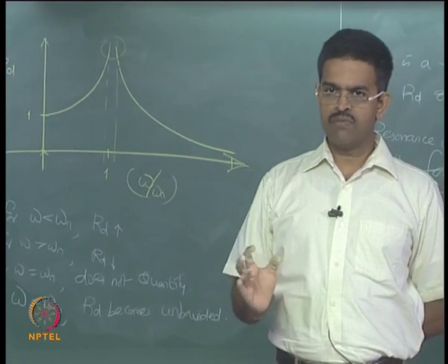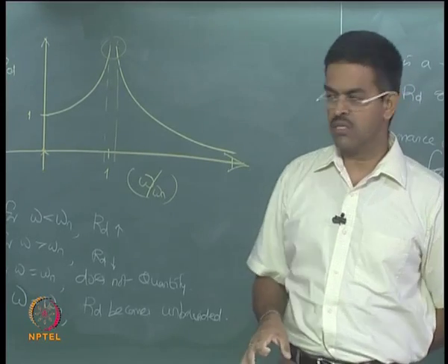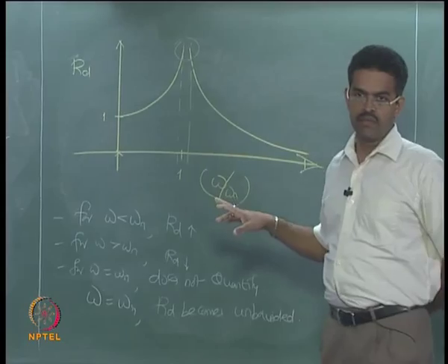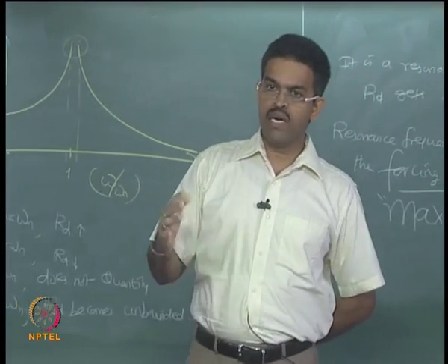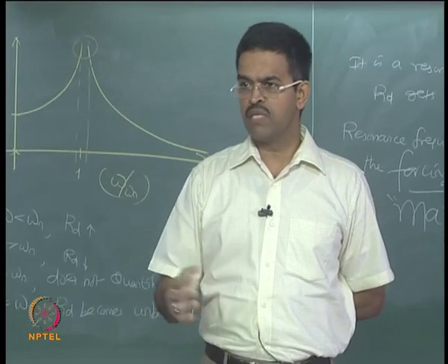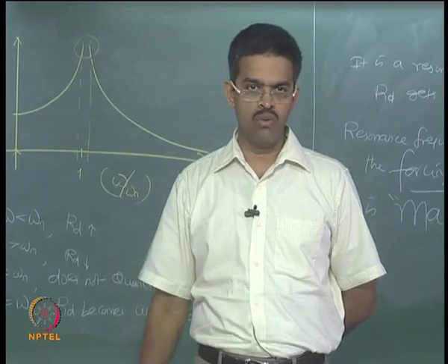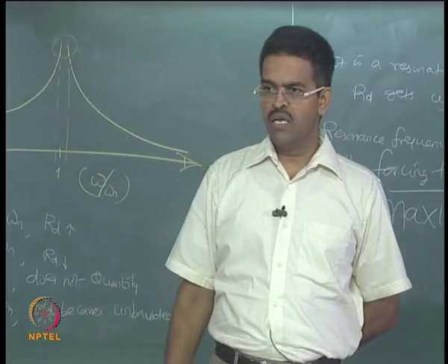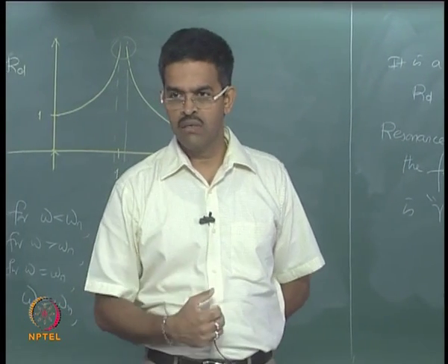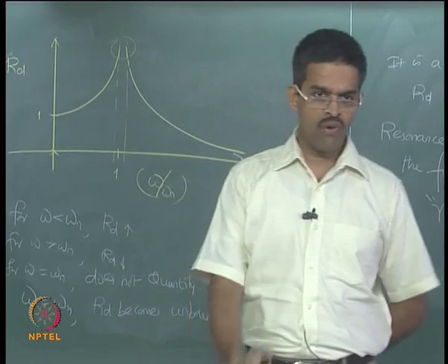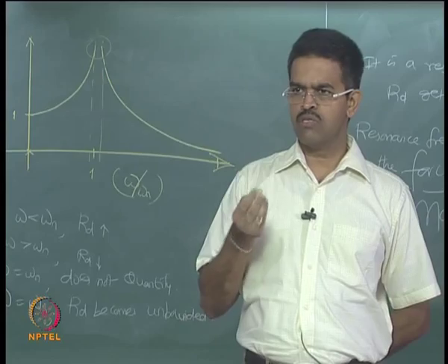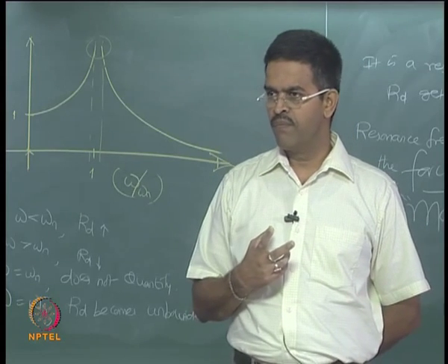Okay, but as far as we understand in dynamics of motion structures, omega n is also varying because of one great advantage, which is the variable submergence effect we have. It also varies with K, I will talk about that later in the second module. That is why I initially said offshore structures are form driven systems, the stiffness is not unique, it changes with time. Stiffness is a function of time actually, it is a very interesting problem which very few structural systems on earth you will have. Okay.